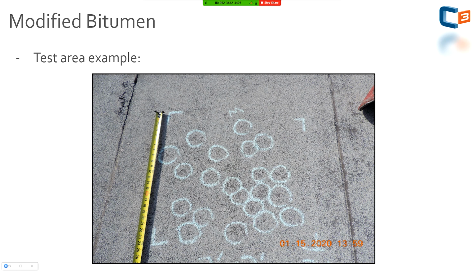Here's an example of a granulated modified bitumen cap sheet. So sometimes these can get tricky, and you'll see that going out there. You see varying insulations and various coatings. This one specifically had an elastomeric coating applied. So it's kind of hard to tell. It's very bright. If you're out in the sun, you better have sunglasses because it's very, very difficult to see what you're looking at. You can see that there's a little bit of dirt gathered in that top left impact mark at the top side there, that top circled area with chalk.